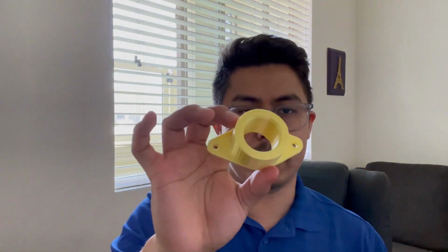Same thing applies if you have a true positional tolerance on this one versus just using the dimensions relative to a couple other features. You can definitely miss the mark if you don't have any datums defined from there. So jump back to the PowerPoint here and go over some of the pros and cons of GD&T.